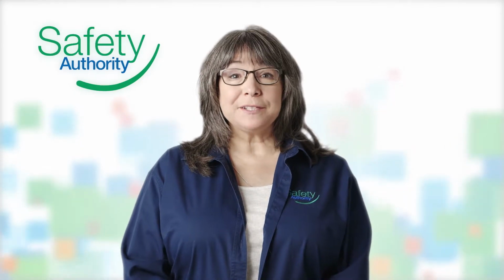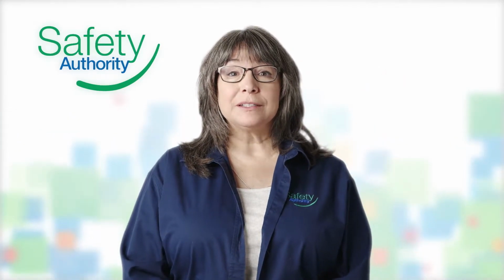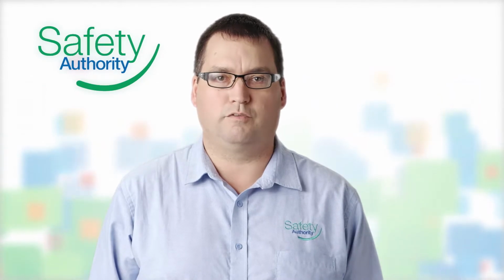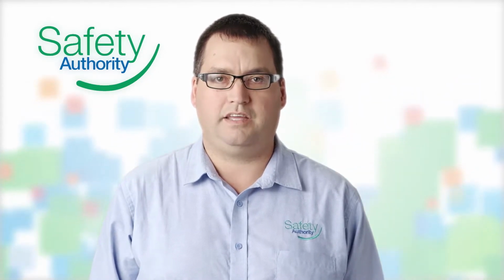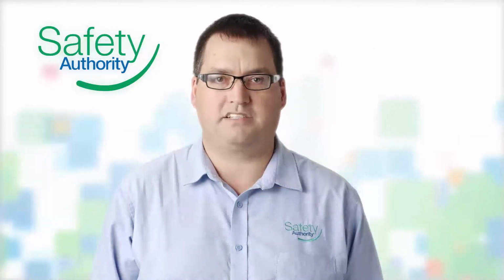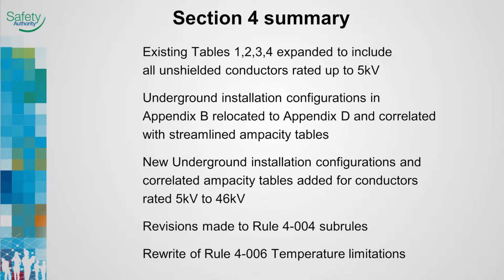There have been some significant changes in Section 4, Conductors. We'll go through it in several parts. Some of the changes in Section 4 have seen a complete rewrite of Rule 4-006, temperature termination ratings, and the underground installation tables being moved from Appendix B to Appendix D. Existing tables 1, 2, 3, and 4 have been expanded to include all unshielded conductors rated up to 5 kV.